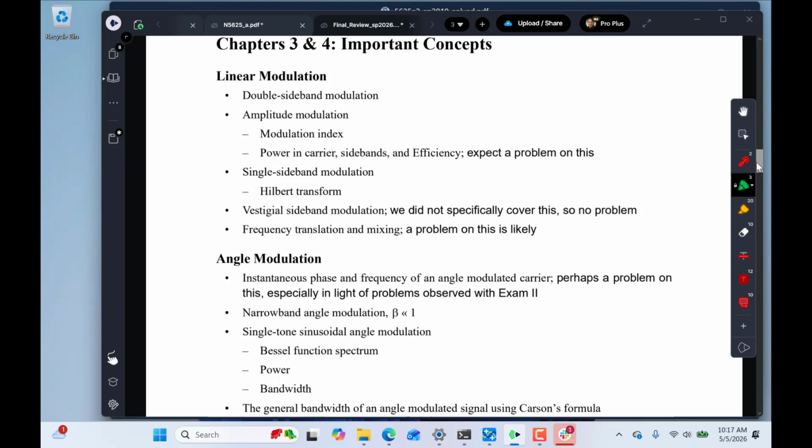But in terms of being able to work with it, block diagrams, double sideband, it's the crux of digital modulation too, but it requires the coherent carrier recovery. So it's what we have to do when we want to do well. Amplitude modulation is what you can do with less investment, especially when it's an asymmetrical kind of a link. And we've talked about that a lot. A lot of people listen, you want to make the lower cost receiver. If only a few people transmit, you put more money into the transmitter.